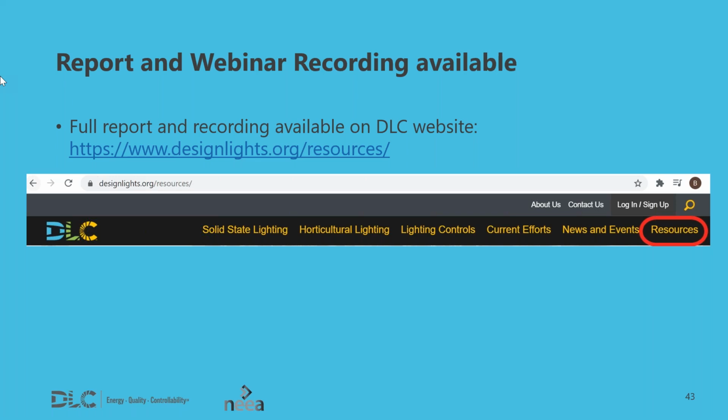The other benefit to high-end trim is that if the light lessens because of degradation, you can turn the fixture back up to continue to have the same light level. But it takes a long time for the light on LEDs to come down to a measurable point where it's going to make a difference, and by that time you may be changing the fixtures out anyway.